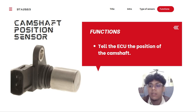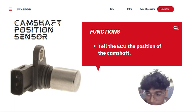Next, the camshaft position sensor. The camshaft position sensor does the same thing as the crankshaft position sensor, but for the camshaft. In theory, the engine can run with a crank sensor alone, but adding a camshaft position sensor paints a much more complete picture for the ECU.